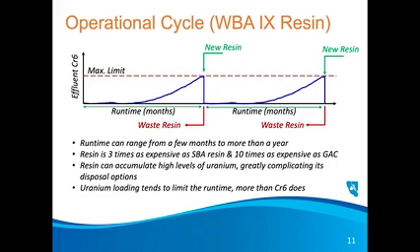It lasts a long time, but it's also at least 3 times as expensive as the typical nitrate type resin that you buy. And on top of that, if you do the math, it's actually almost 10 times as expensive as GAC. So if you think of GAC replacement and you have a good sense of how expensive or how inexpensive that is for a certain system, this is about 10 times that on a cubic foot basis. So it's a significant cost.